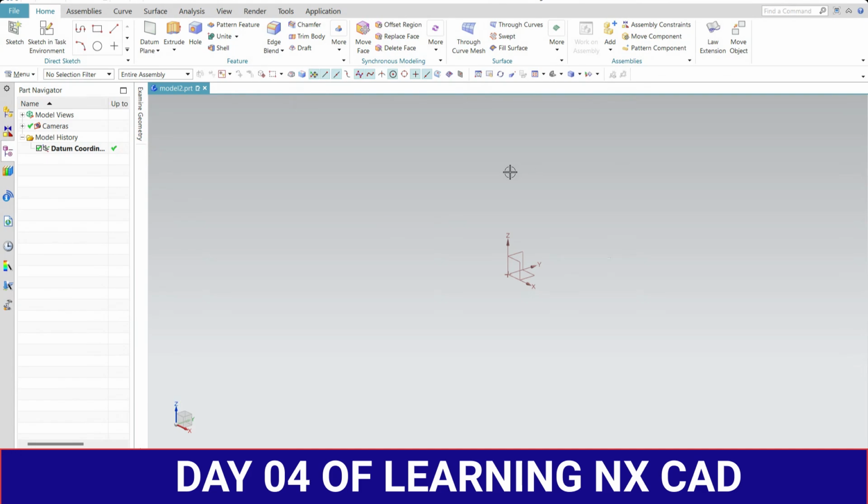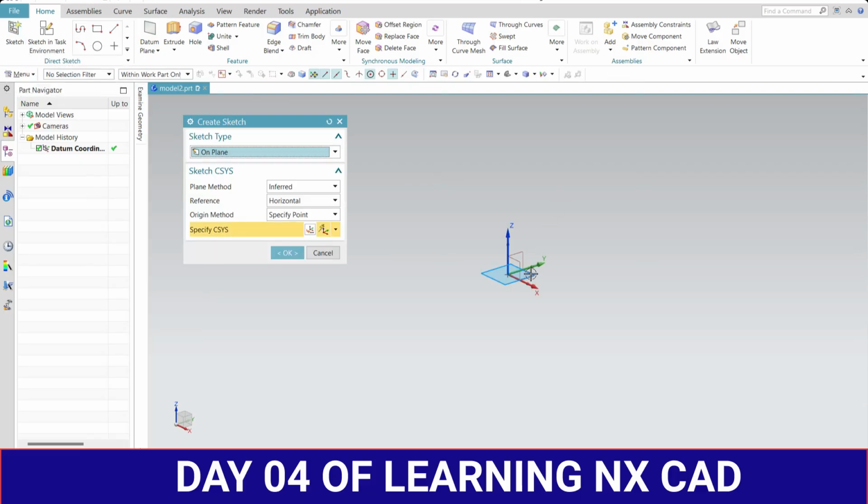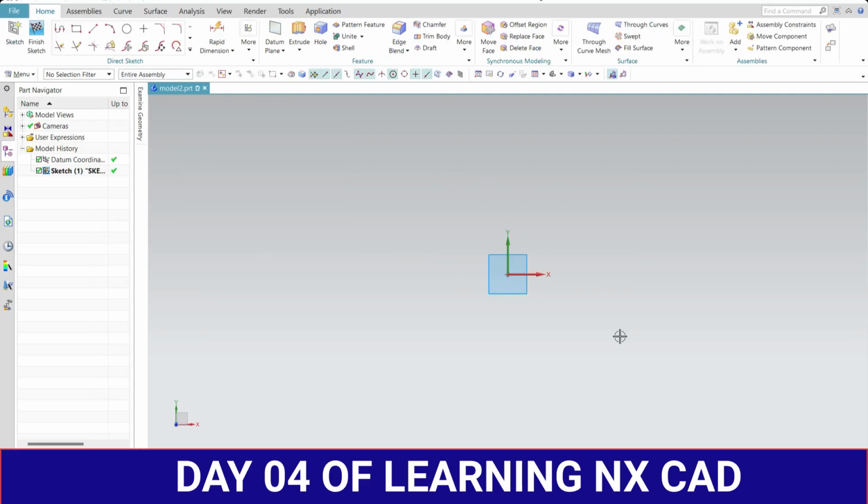Welcome to day 4 of learning NX CAD. In this session, we'll understand the circle type and arc type. For that, first I'll select the sketch, then we'll select the plane here, and then click OK. Now we are in the Sketcher workbench, and here we are getting the command of circle.